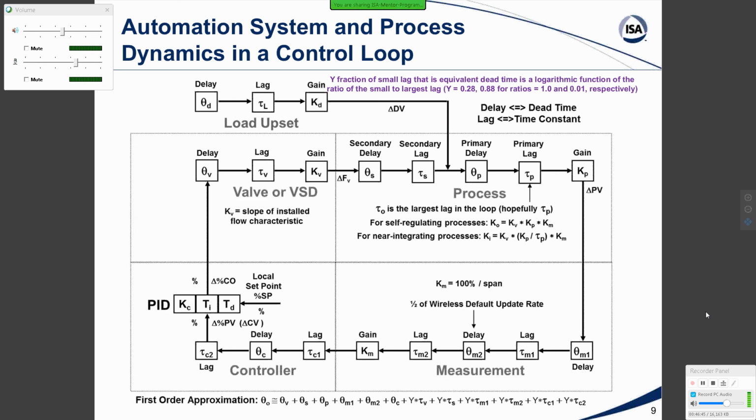And also we'll see how to set lambda not as a factor of a time constant, but as a dead time, like maybe 2 dead times, 3 dead times. It kind of unifies the tuning methods, and we can get on a similar basis.